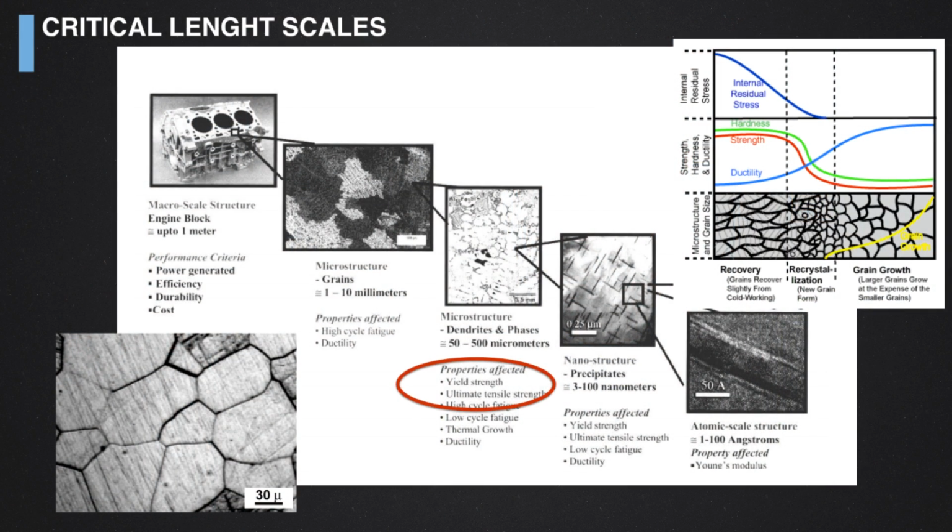Let's go now to the yield strength. So the crystalline structure is influencing all the mechanical properties. In particular, if you have very big grains in a material, in a microscopic object, you take the risk to have also a very brittle material, because big grains also mean that you have not a perfectly homogeneous structure. If you are able to reduce the size of the grains, you are also increasing certain kinds of properties, in